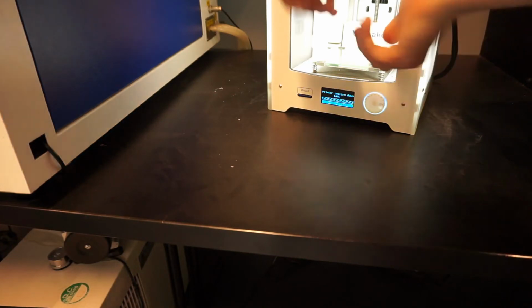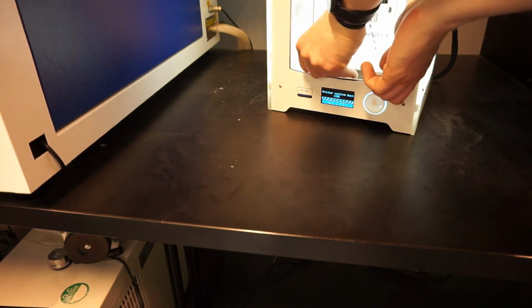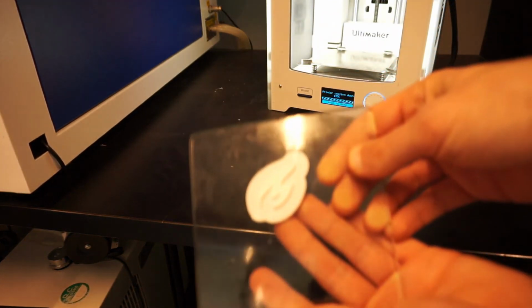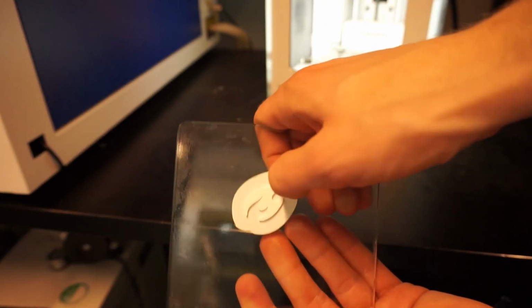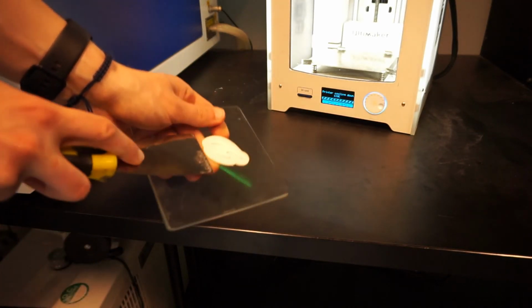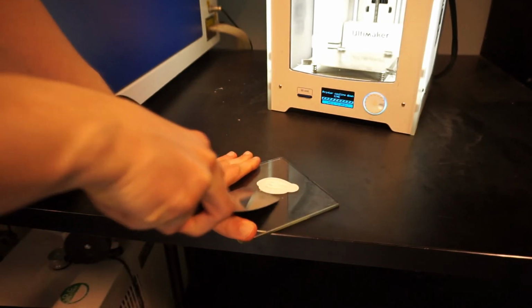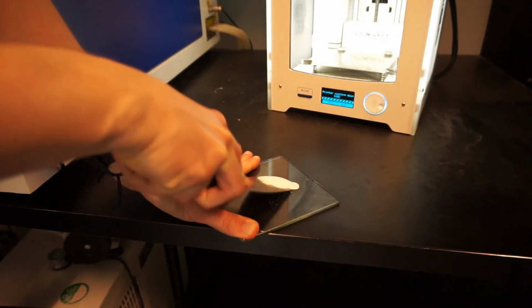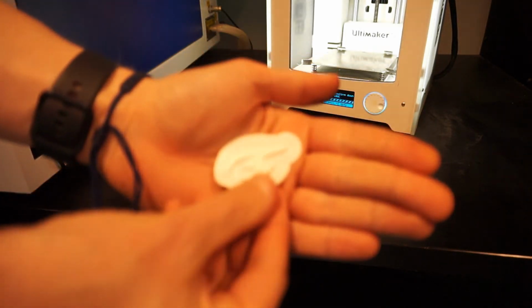The print is now finished. You can remove the glass plate with the build on it. The build is probably sticking to the plate, but you can remove the build using a special tool. This tool is usually somewhere around the 3D printer. The easiest way to remove the object from the glass plate is to use the tool in short, fast strokes. As soon as the tool is under the edge of the print, you can simply remove the rest of the object.